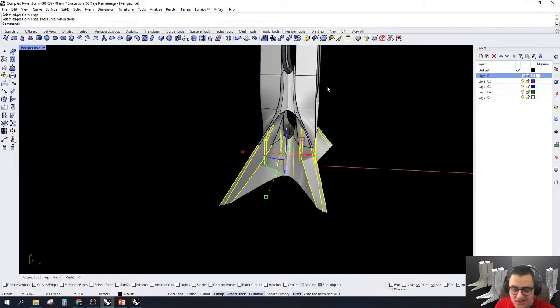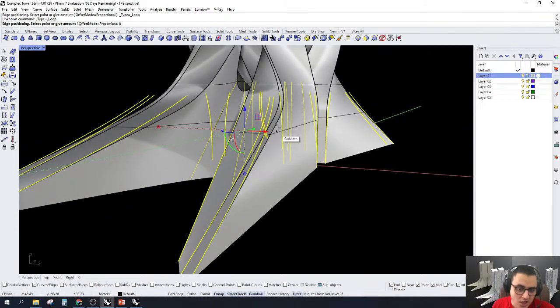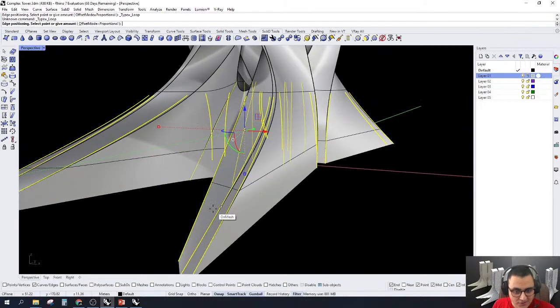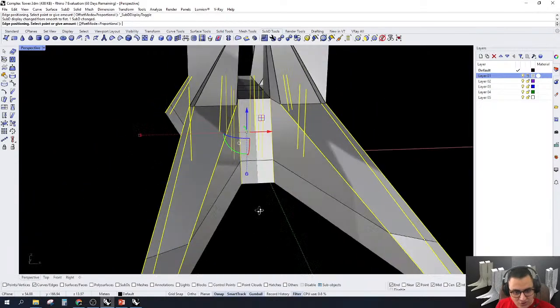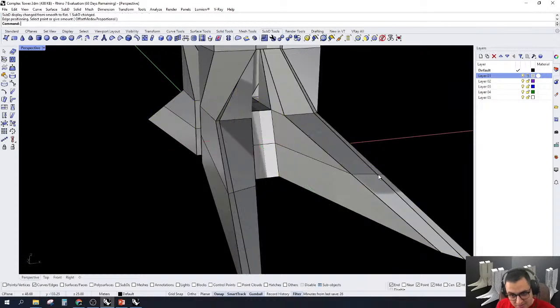Maybe you will select multiple curves, and after that you will lose them because you simply didn't hit enter, which I face all the time. And here we are. Simply we will add a curve like this. When you are working in the smooth mode, it's not easy to work with, so simply hit the tab, so it will be easy to see where the middle part is. And here you are.